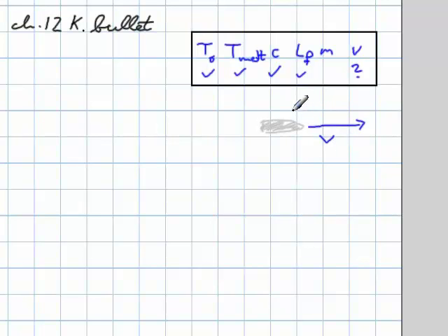It starts at 30 degrees Celsius, heats itself up to the melting temperature. That means in order to get there, a certain amount of heat has to go in, which is the specific heat. So c times m times delta T. This here is the almost 300. It's like 297.3 Celsius degrees. And then it has to melt, which means there has to be more heat going in order to melt it. And I could call it Q_F, the one for the latent heat of fusion. So I have to add that to that.